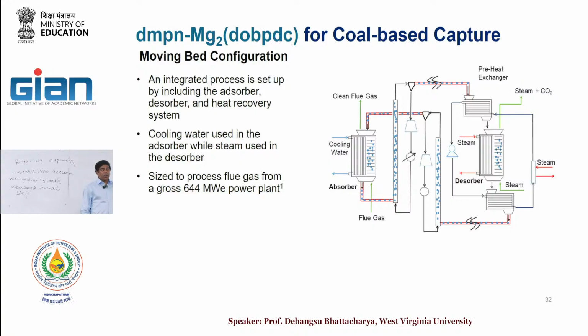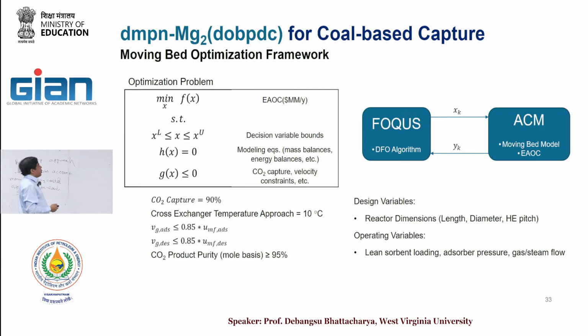Can this be done commercially? Yes. The only process that I know where they have actually manufactured and tested this is one where these are stacked on top of each other. So it's a single unit that actually helps them. It's multiple segments, and everything comes at the bottom, and then they transport it to the top. This pneumatic transport is generally very standard and has always been used for solid transport. But instead of having it at multiple places, you just have it once, and all these beds you can stack on top of, or below, each other. So they found commercially that made more sense.